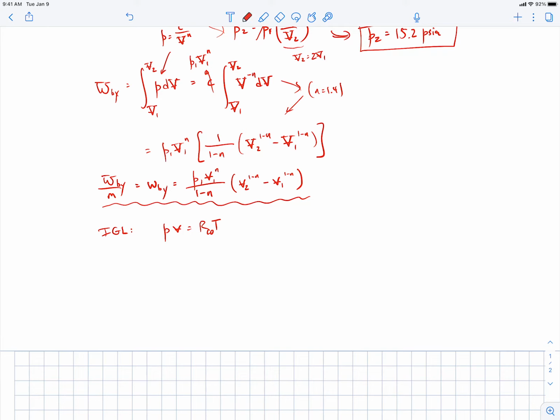The way you could calculate it, for example, is you would just take the universal gas constant and divide it through by the molecular weight or molecular mass of carbon monoxide. To give you a feel for how you do that, if you look up the universal gas constant in these kind of crazy English units, it's 1.986 BTU per pound mass mole. Per pound mole is just a common way to say it. And there's also degrees Rankine in the denominator. So that's the universal gas constant.